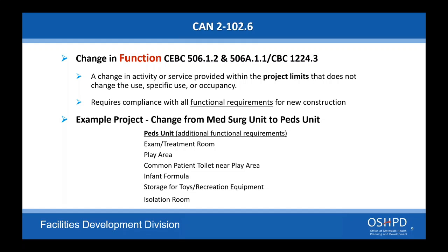If you're changing the function of the space, you have to meet all the functional support requirements for that space, such as we use the example of the med surg to pediatric. If you're not changing the function, and you're doing a remodel within a med surg to med surg and just remodeling the space, then the existing support spaces, even if you have an old soil utility room that's not being touched, you do not need to upgrade it. It goes to the example about the patient rooms that are out of compliant with current code, but were built in compliance with the code at the time it was built. The same thing would apply.